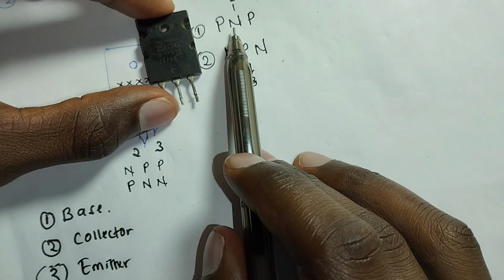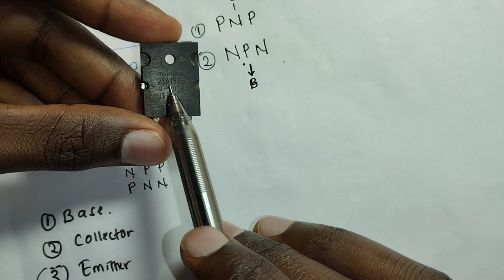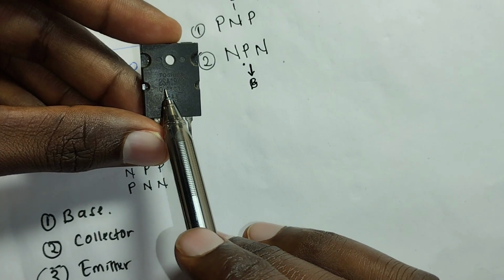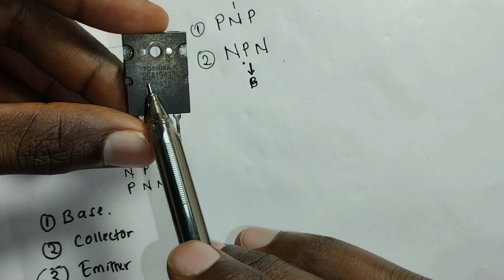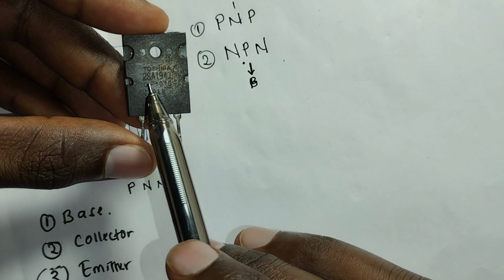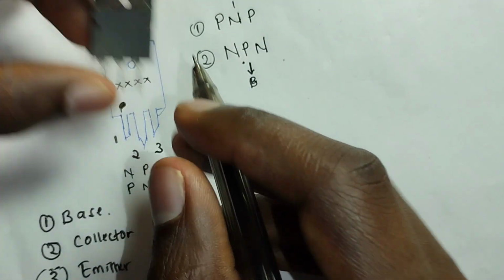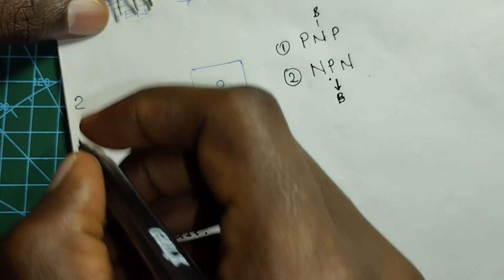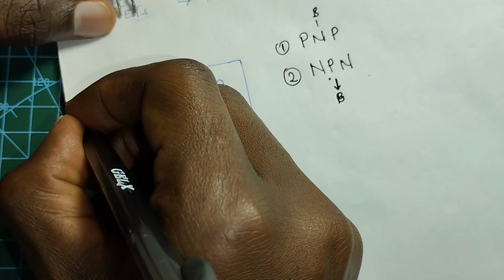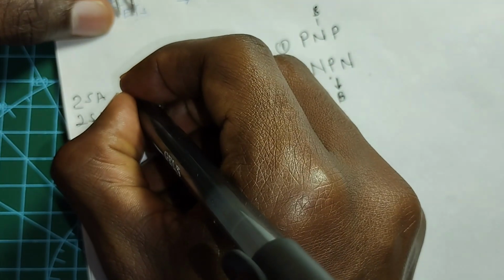In knowing which transistor is a PNP or an NPN, this is where the naming scheme comes in. Now in this naming scheme, where we have 2S, the first letters of the alphabet, A and B, stand for PNP. Okay, so if you have a transistor labeled 2SA or 2SB, that one is a PNP transistor.